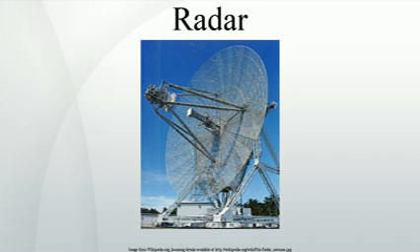If the transmitter's output is coherent, phase synchronized, there is another effect that can be used to make almost instant speed measurements. No memory is required. This is known as the Doppler effect. Most modern radar systems use this principle, in Doppler radar and pulse Doppler radar systems, weather radar, military radar, etc. The Doppler effect is only able to determine the relative speed of the target along the line of sight from the radar to the target. Any component of target velocity perpendicular to the line of sight cannot be determined by using the Doppler effect alone, but it can be determined by tracking the target's azimuth over time.